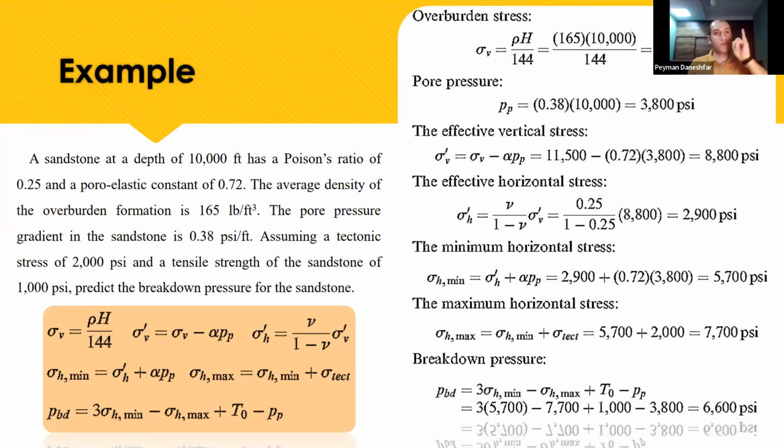Predict the breakdown pressure for the sandstone. First of all, we should find the vertical stress, or overburden stress. After that, we can find the pore pressure.